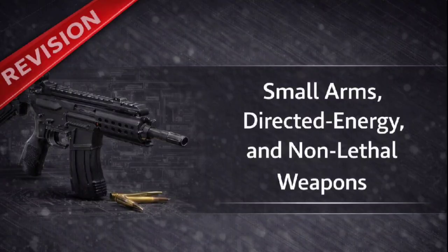Now, to ensure reliability, especially on systems that fire a lot, engineers often add recoil boosters. Can you detail the two main types? We can enhance the available energy with a recoil intensifier. This is a specialized chamber located at the muzzle. How does that work? It traps the propellant gases that follow the bullet, and it uses them to provide an extra push backward to the barrel. This ensures the system cycles even when it's dirty or you're using lower power ammunition.